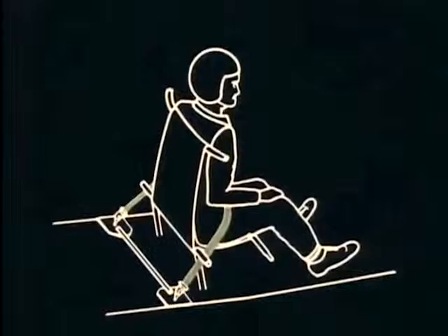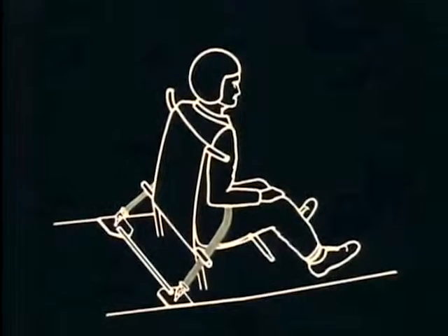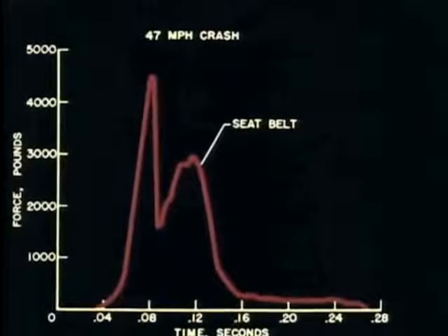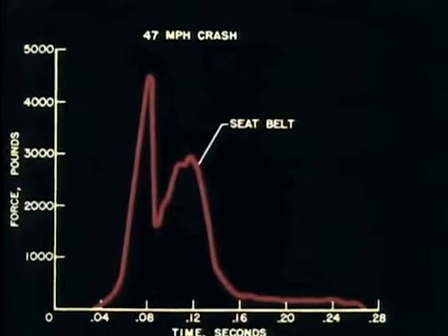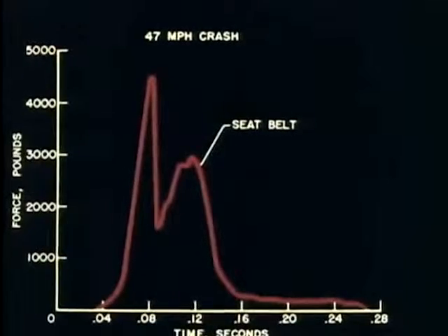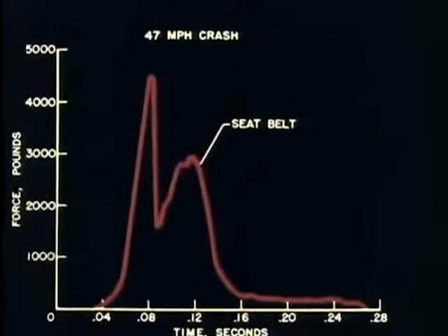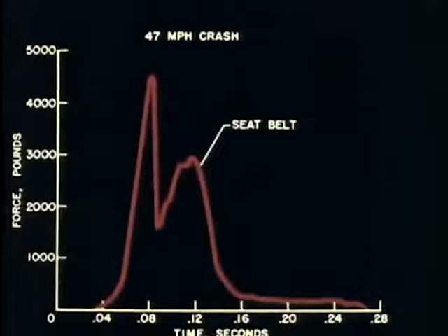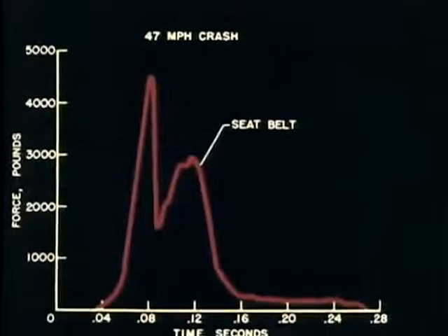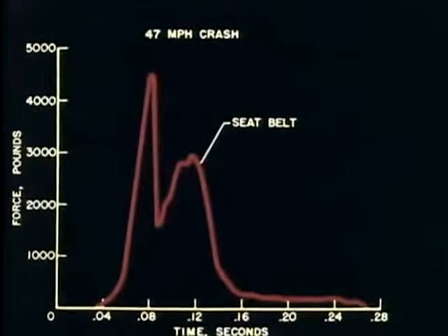The restraining forces in the seatbelt were higher when the passenger was restrained by a seatbelt only, even when the impact speed was reduced from 60 to 47 miles per hour. During the 47-mile-per-hour crash, in which the dummy was restrained only by a seatbelt, peak seatbelt forces were 4,400 pounds and 3,000 pounds, as compared to a peak of 4,000 pounds for the seatbelt for the 60-mile-per-hour crash. Seatbelts and harness capable of withstanding these dynamic loads can be comfortable and light in weight.